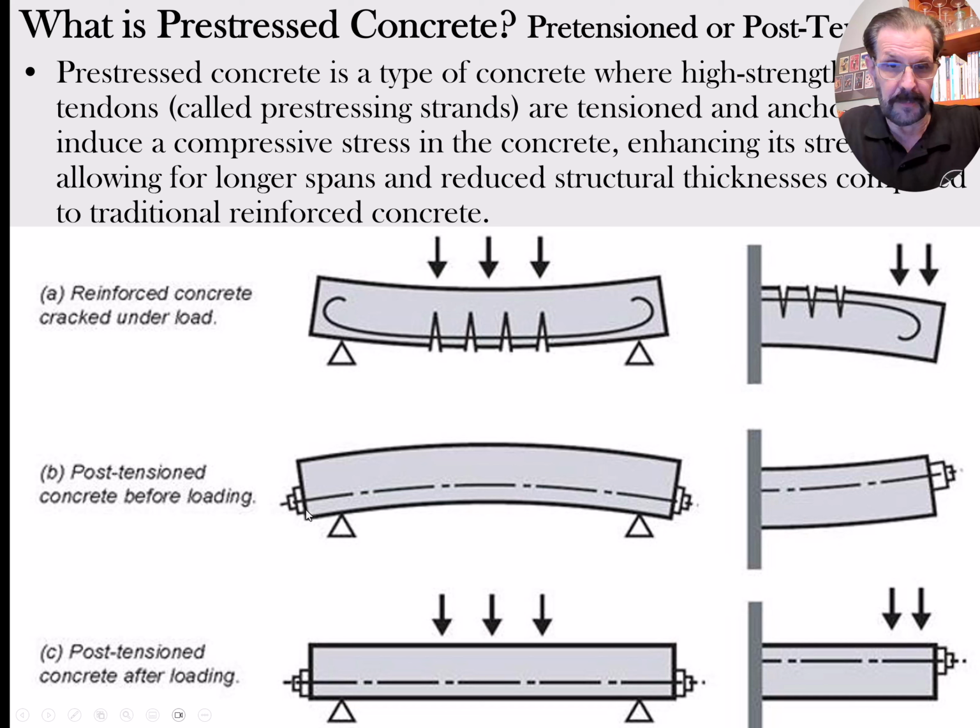And it's literally, if you have it in the bottom of a beam, if you get enough post-tension cables going, you can actually compress the concrete enough with these that it's actually causing the beam to have a crown in it, where it can compress more on the bottom and it's in tension more on the top, just like sometimes you can see in wooden beams. When we're setting up a 2x12 or a big heavy timber, if there's a crown in it, we typically want the crown to be up, the curve to be up, just like this beam. And then when you get the load on it, then the idea is that would level it out again.